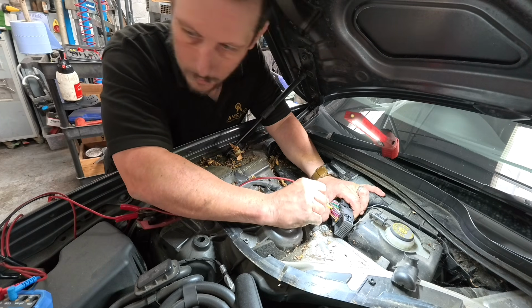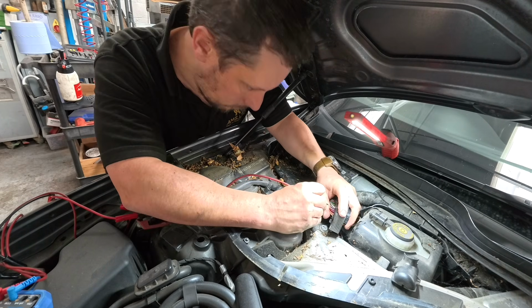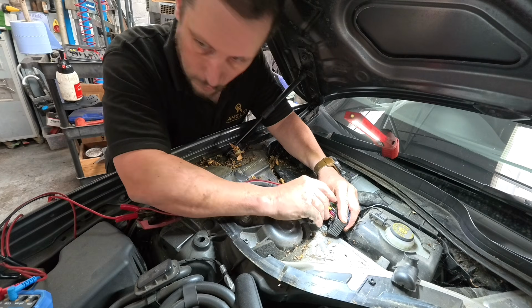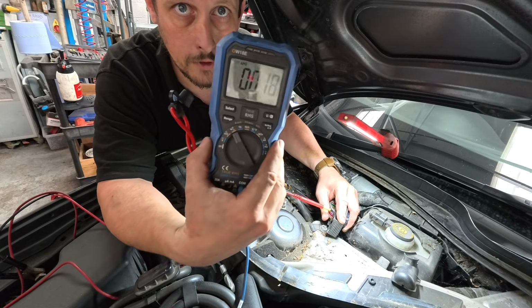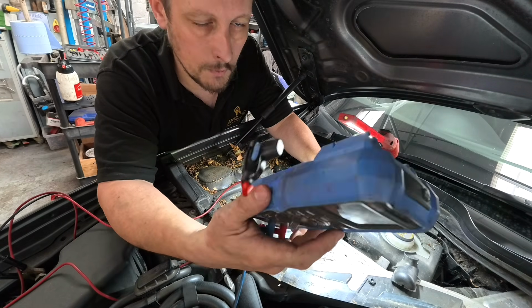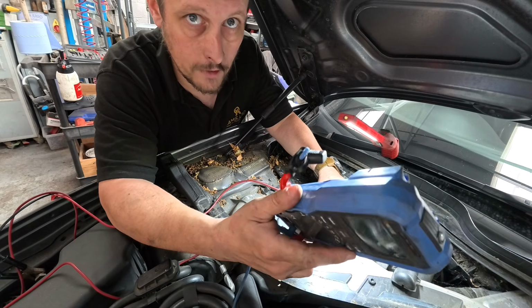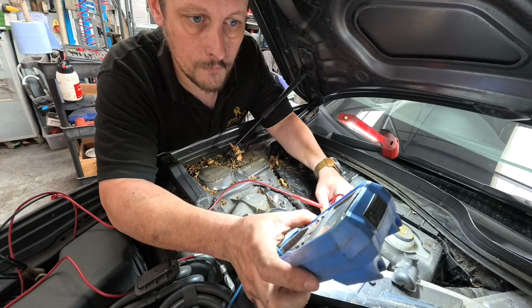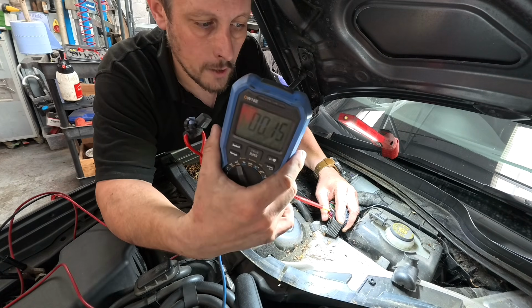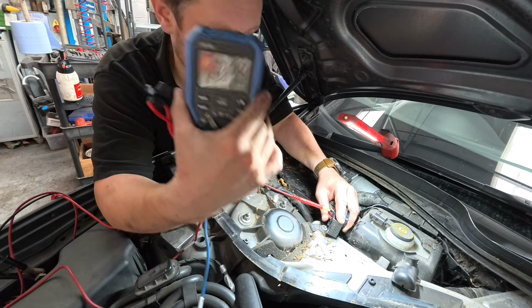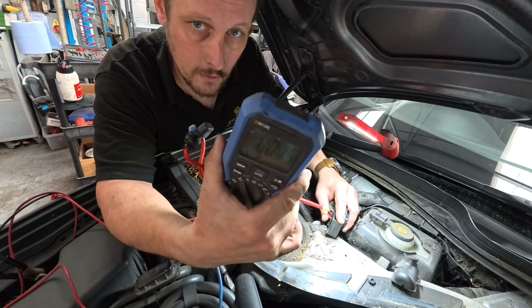So if I back probe into there, I've currently got this set up to look for resistance, ohms testing, okay? We've got very little ohms, but I'm not worried about load or anything like that currently. All I'm worried about, because I know the load's okay because I've tested it at the other end, is have I got the right wire, okay? So I've got the right wire, that's all tickety-boo.